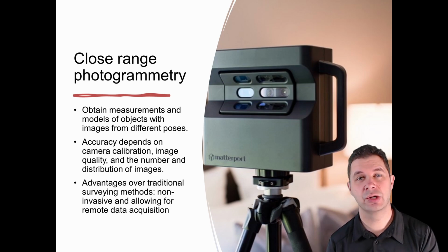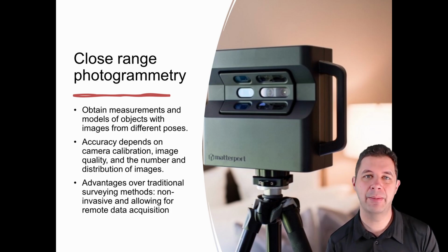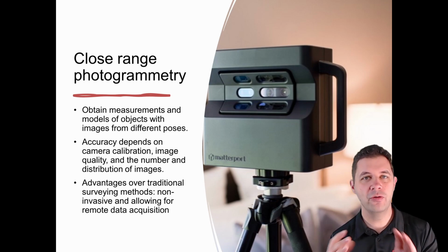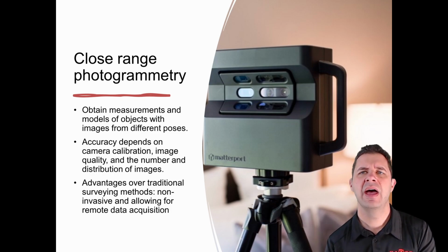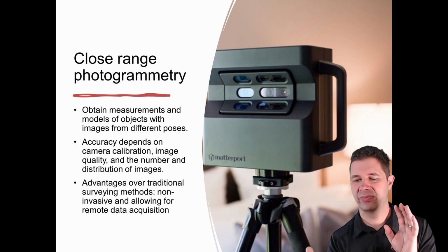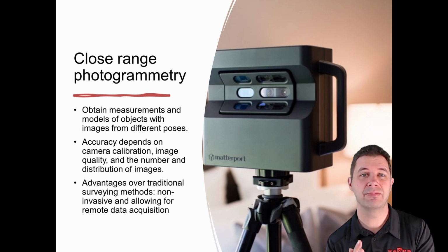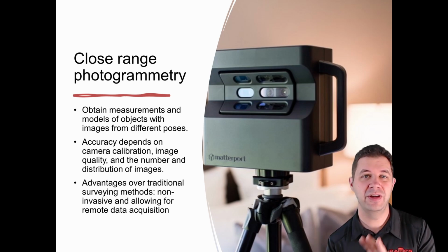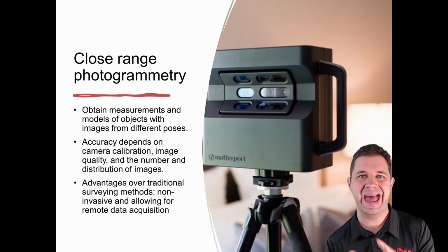Our accuracy depends on a number of different things. For example, our camera resolution, the amount of overlap that we have between our photos. It also depends on the number of photos we have and things like the surface of the image. Some surfaces have very few features, and it's harder to do matches accurately between different images.